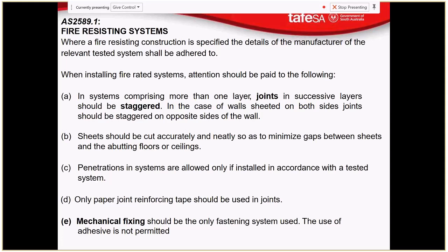So we can actually use a timber framed wall as a fire separation wall. We're not going to design them ourselves because for our individual practice or individual jobs, we are not going to have the resources required to do all the testing. But various different gyprock or plasterboard manufacturers have designed and hence specify their own systems for fire-rated walls. Yeah, party walls.